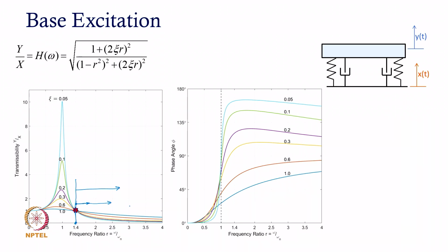Maybe look at this point. Yes, you do get some attenuation. So, the amplitude of course decreases, but when you want to reach this point, you do pass through this resonance anyways, right. So, as you keep on increasing your cruising speed, you will eventually end up crossing the resonance. What do you expect and what do you want at the resonance? The damping to be the higher value.